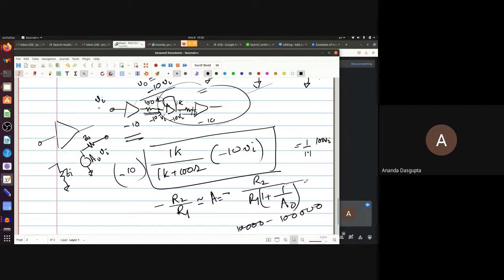When people design a building, they design it with certain amount of strength of materials in mind, how much load the concrete will bear and so on. Of course, real concrete does not match those ideal numbers. But the design is made in such a way that even if your parameters were off by quite a bit, your final behavior of the final output system should be the same. You don't want your building to collapse just because somebody used another sack of concrete, which was of an inferior quality. Okay. Of course, if you entirely use inferior concrete, your building might collapse.